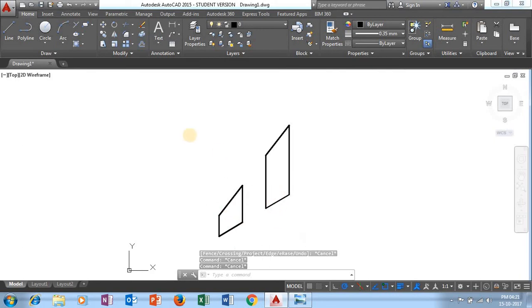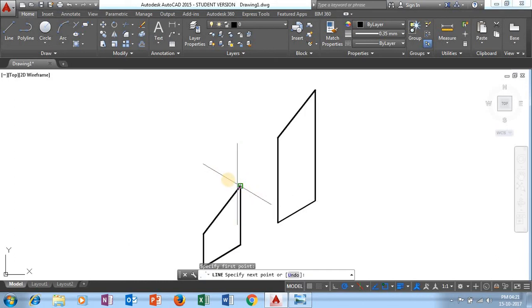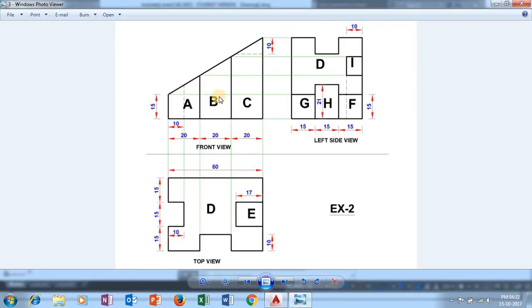Now we are going to generate surface named B. So take a line. Now from this particular point we have to travel in left hand side direction in the positive way, that is 150 degrees. Just give a click here and in the 150 degrees direction, and this particular length is going to be 10 mm. So type 10 and hit enter and hit escape key. See, if you guys can see here, this is your surface B and if it is vertically projected here, you can see that surface B is having certain distance from surface A and surface C. That particular distance is given as 10 mm. So only I had taken 10 mm over there.